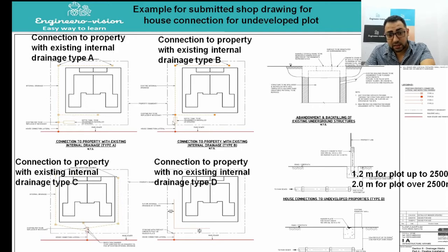But in this case, the septic tank is in our way to the connection. So we have to demolish the septic tank at the beginning, as per this cross section and as mentioned in the specification. Then we will do the overpumping from this inspection chamber into our main network until we finalize our work in this area.